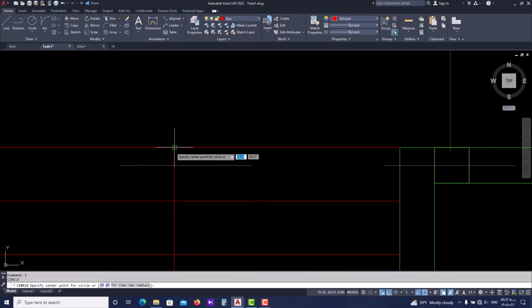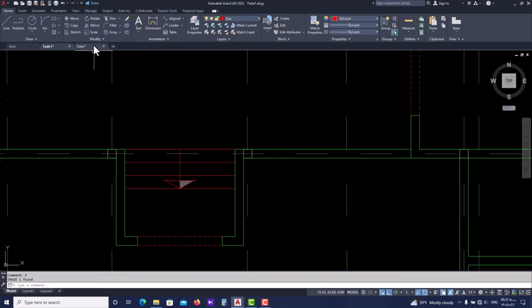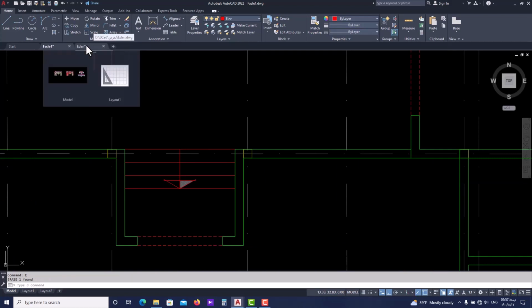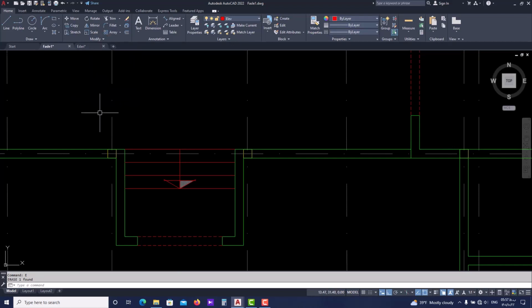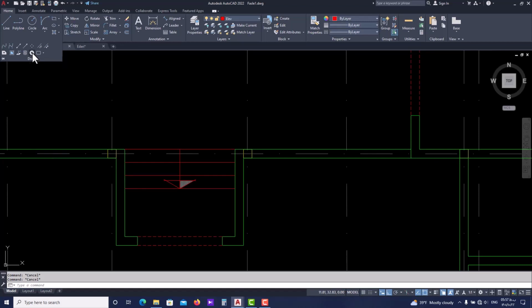Now, because we haven't talked about circles yet, we can use another command here. We can use donut, not the one that you can eat, the one that you can use for your drawings. Let's check the icon here. As I said, we use it for our drawing, so it is in the drawing box. Here we can see its donut shape icon as well. We can select it from up here, or you can use its shortcut key, which is DO enter.